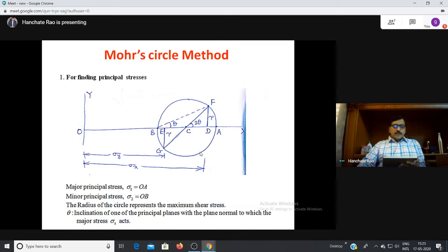GRB Prakash asks: Sir, what is the difference between conventional concrete and pre-stressed concrete? Mr. Prakash, I have explained to you that concrete is very strong in compression, whereas it is very weak in tension. So to resist tensile stresses, one method of reinforcement is by keeping steel reinforcement bars. That is what we call reinforced cement concrete. The second method we use is pre-stressing the concrete.